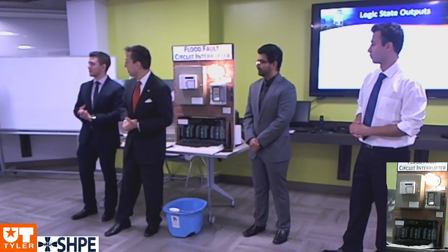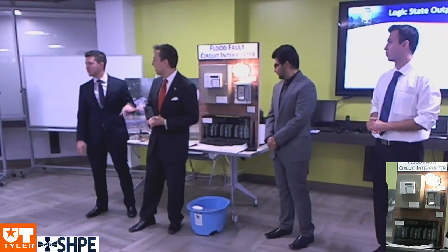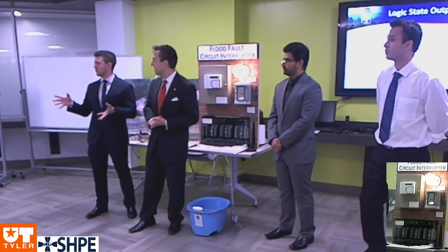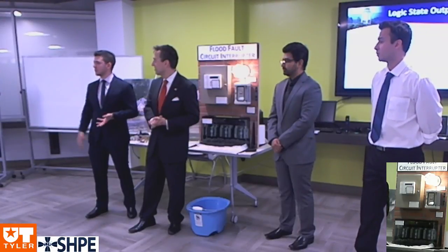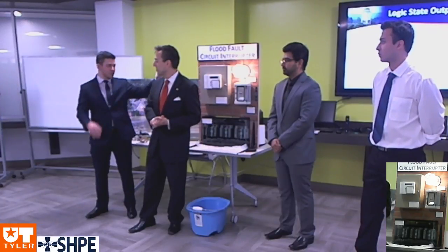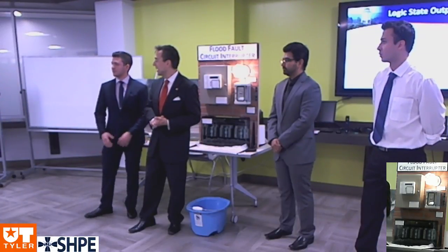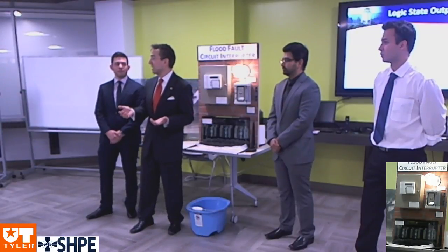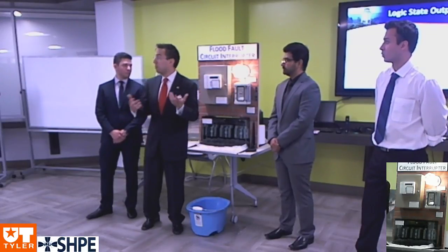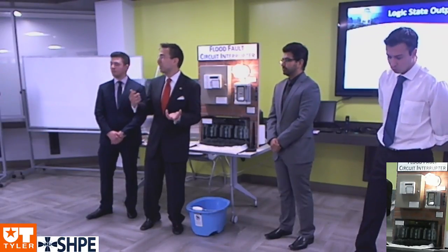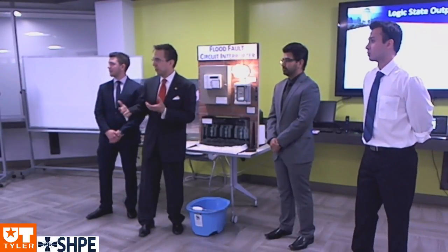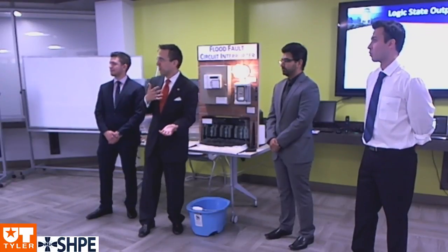Yeah. Because we have about 6 of these switches, we can have 2 of them be false alarms, because all we need is 4 of them to be detected in order to trip the switch. And the normal fault state for these devices is to fault on. That would be recorded and reported by the control system. So an operator monitoring the system could see that switches are becoming faulty and might be able to, among other things, schedule a service replacement. And for us, that's why we can balance low cost with failure modes.